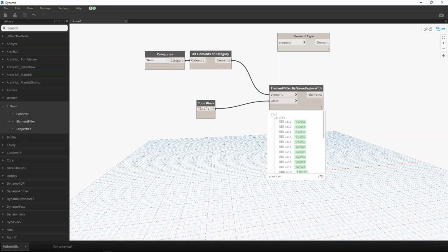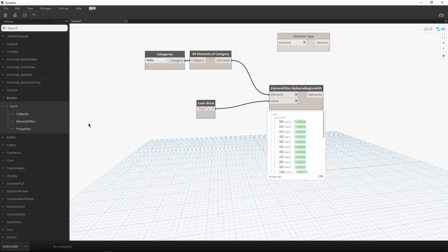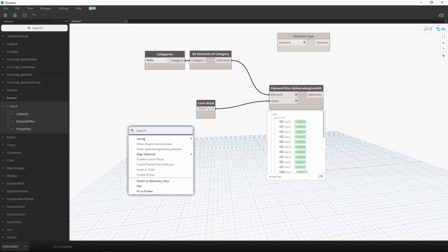You're like, oh, there's too many levels, we got to remove these. But then if you remove a level, what happens to all the elements on that level? They disappear, they get deleted, right? And so there's nothing in Revit that allows you natively to say, show me all the things that are on level 2. You can't do it.